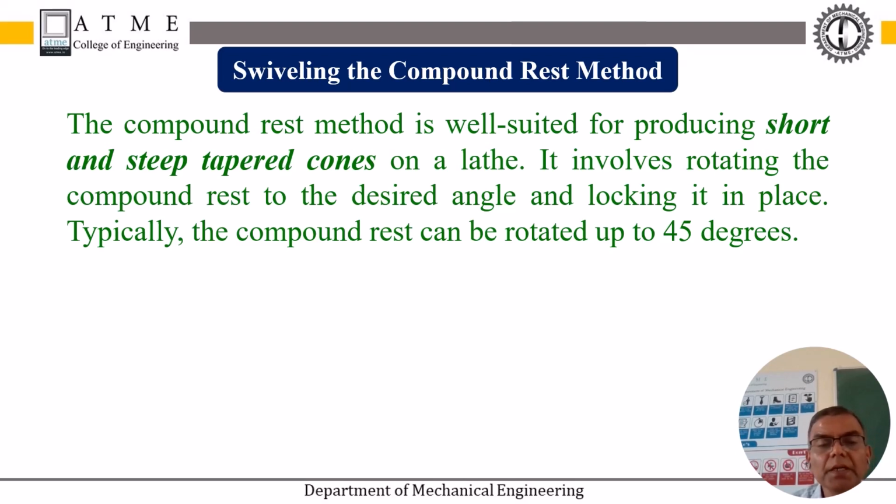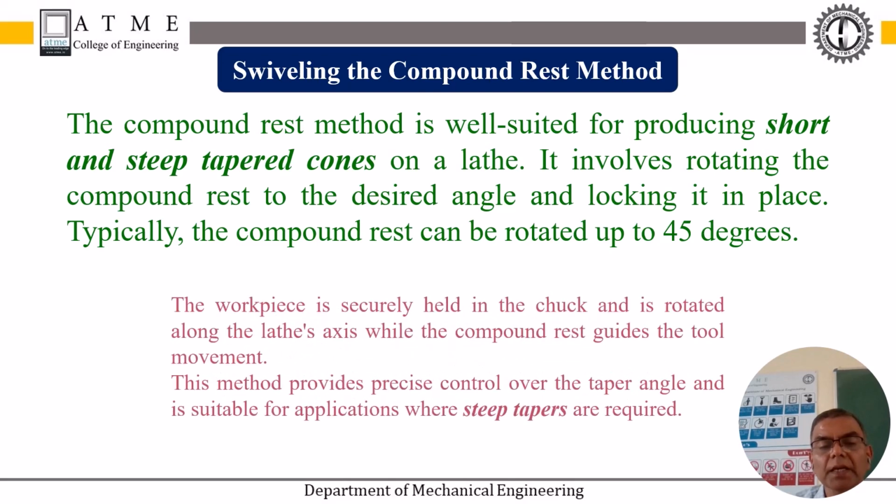This method is recommended for a steeper angle and a smaller taper length. It involves rotating the compound rest to the desired angle and locking it in place. Typically, the compound rest can be rotated up to 45 degrees.